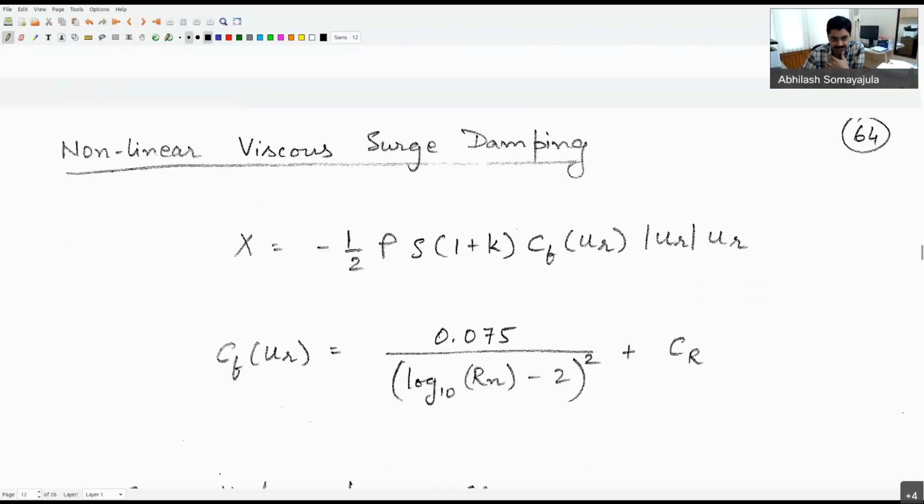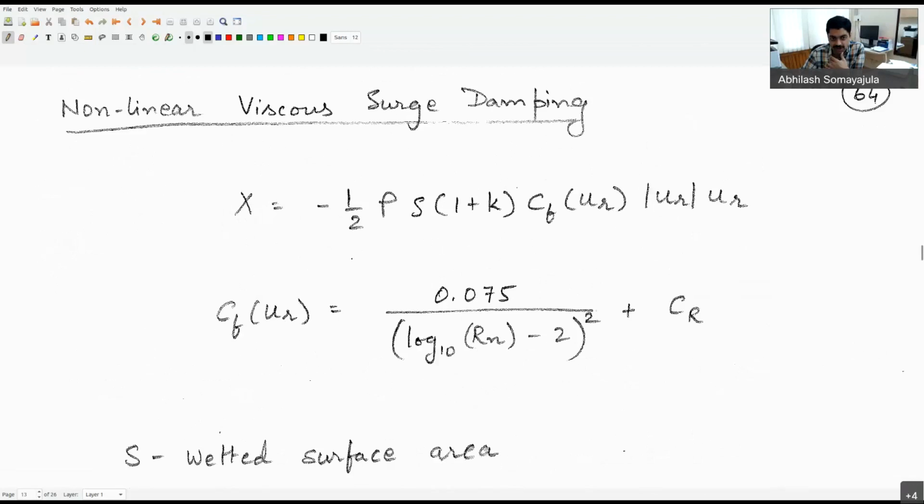Okay, now let's proceed further. Today we'll talk about the non-viscous, nonlinear damping part, and we'll primarily focus on a couple of methodologies. First we'll talk about how we can apply a first principles approach to approximate those dampings. And then we'll look at the natural Abkowitz model, where we are not doing a first principles approach. I'll try to tell you the difference between the two approaches.